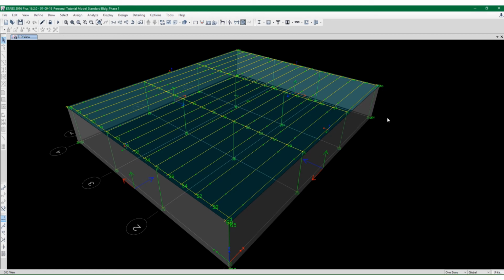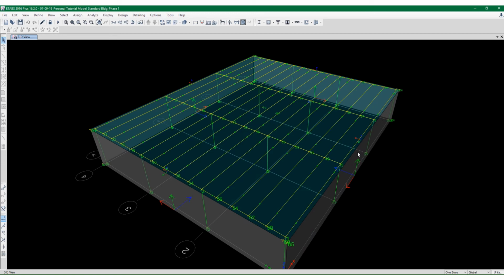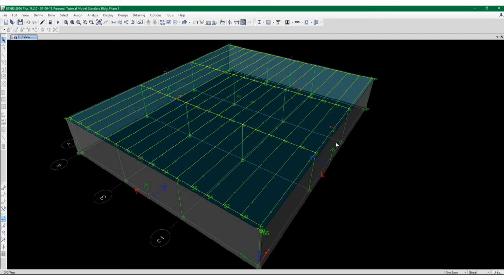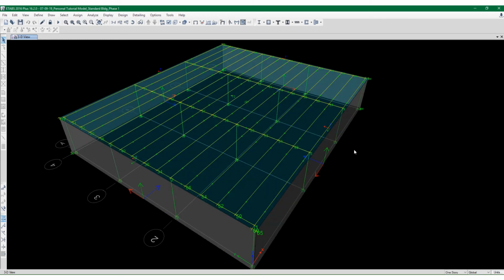Okay, picking up from where we left off, we had completed the analysis, gravity and vertical, gravity and lateral, and we realized that even though the analysis ran and the member sizes were analyzed, we can determine the capacity ratios, we still had deflection issues at the edges of the deck itself.